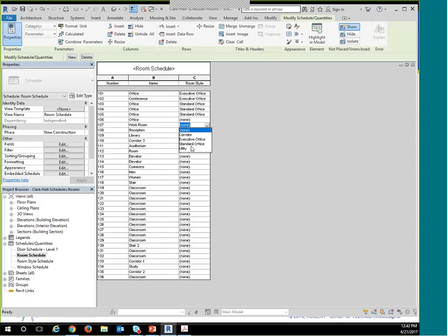Here's a workroom. It's a utility space. There's reception, you know. So as you can see, you just kind of keep on going down and adding in the various things, the type of information that you need. And it goes back to that room schedule. And so you need both of them when you are putting them on in your construction documents, but at least you don't have to go back and add every single space that has this carpet or that carpet and that sort of thing. So that's how our key schedules work.